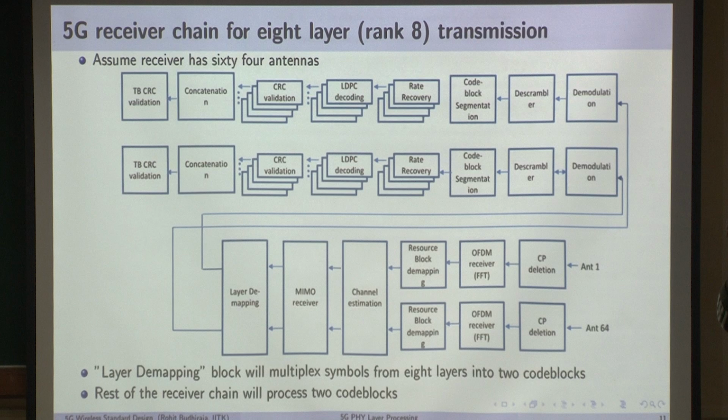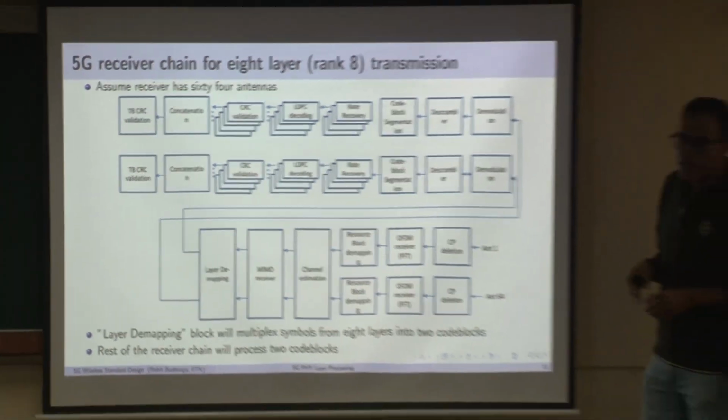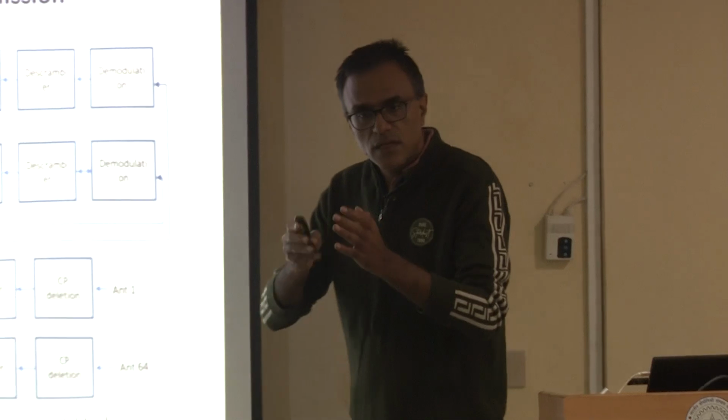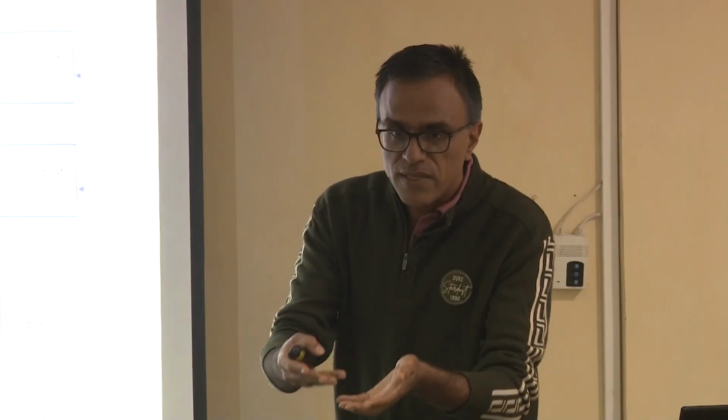So without MIMO, if it is 1024 QAM, on each resource element you are transmitting 10 bits. So whatever resources you had might not work to execute that kind of processing. And look at the complexity: the complete processing, at least at the base station side, has to be finished within each slot.